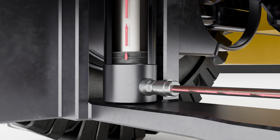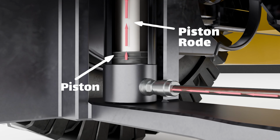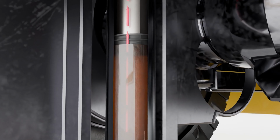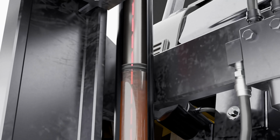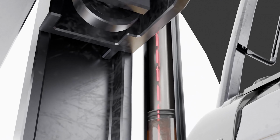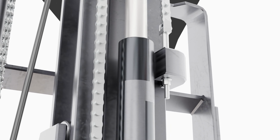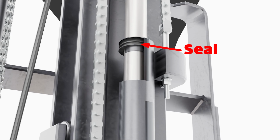Inside every hydraulic cylinder, there's a piston sealed tightly inside a smooth, honed tube. A piston rod is attached to the piston and runs out through the front cap of the cylinder. Hydraulic oil enters the lower chamber and pushes on the full surface area of the piston. Because hydraulic oil is pressurized and incompressible, it forces the piston upward. As the piston moves, it carries the rod upward with it. The cylinder's front cap has seals that allow the rod to slide out while keeping all fluid trapped inside. The rear cap seals the back of the tube so pressure doesn't escape.